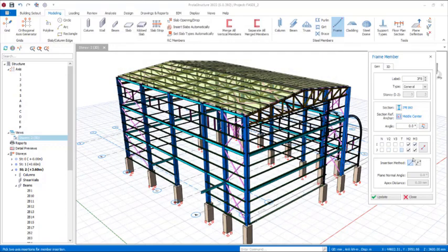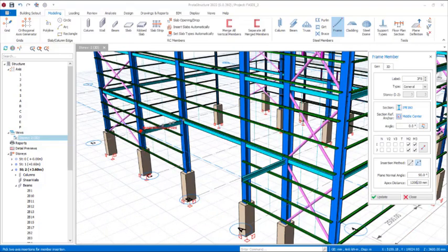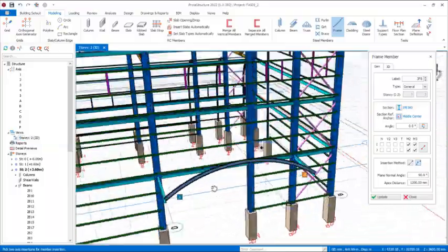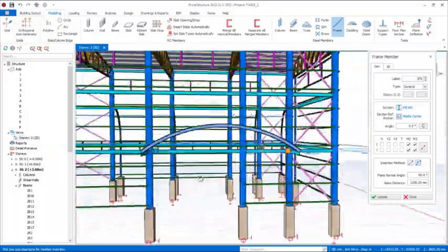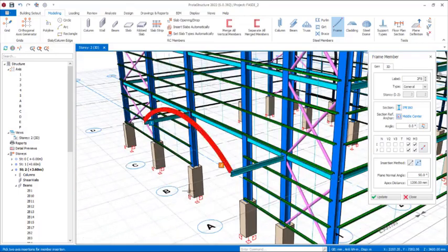All right, so we are going to be inserting both sides. I have these provisions checked very well. So I click on this curve construction method. I will also use 90 degrees. Then I will consider it to be 1200 millimeters, the radius of the curve. So I pick this point first, come all the way, pick this other point to place the curve just like this. All right, so the radius is not too deep.